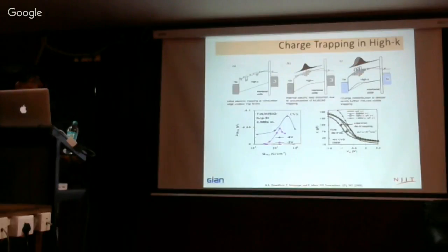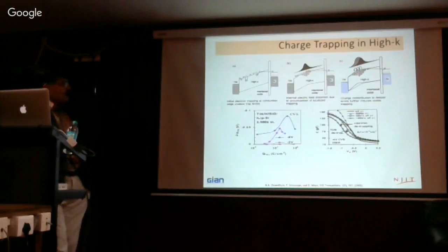And then the interesting thing is you can leave it over time and there will be some detrapping. So there's an initial volt detrap, let's say this is the initial structure. Then you move because of this flat band voltage shift. If you leave it over time, it will move back. That is actually because of the shallow traps.